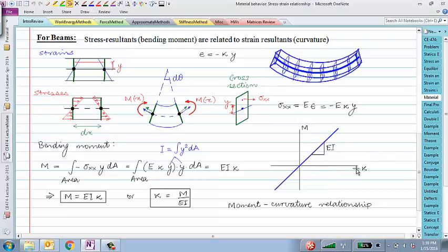And maybe one way to visualize this curve or this plot is this. If I have a perfectly straight beam, no moment anywhere, what is the curvature here? Zero. No moment, no curvature. If I apply some small moment at the two ends, M, right? What would be the bending moment diagram of this beam with M moment here and M moment here? Anyone? Just a rectangle, a constant moment throughout the length, right? M here, M here, it's a constant moment throughout the beam.